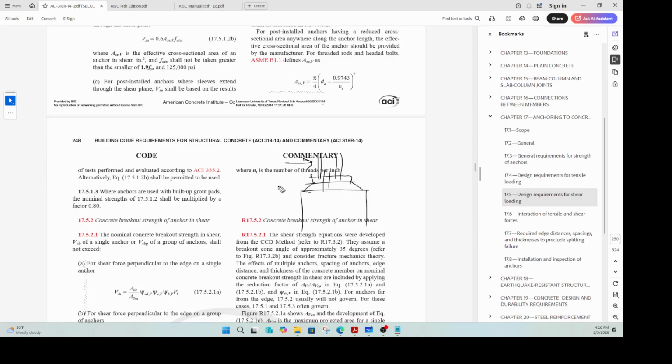When the shear load from the column comes, the load gets transferred onto this interface here, but the anchors start getting engaged at this location. So there is an additional moment. Let's say this is e, then there is an additional moment getting generated on the anchors. Now, when you have a moment and shear combination, your shear capacity has to be reduced slightly, right?